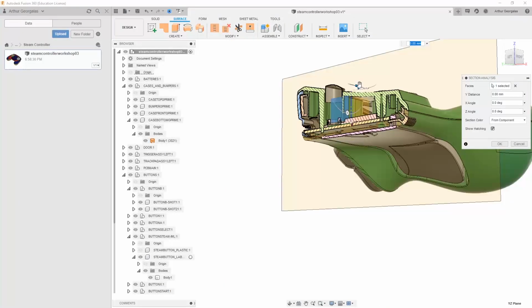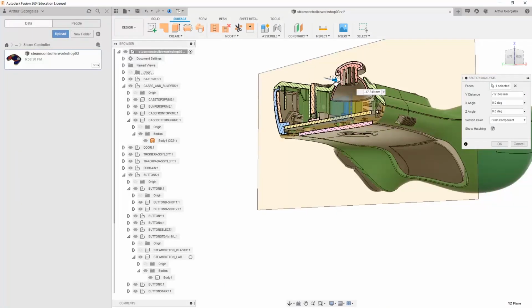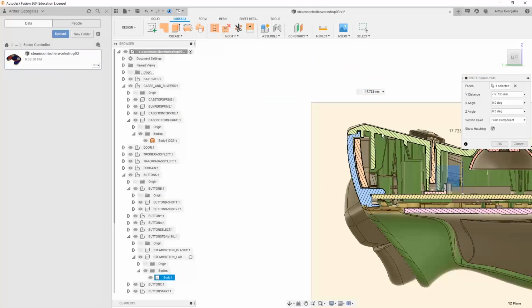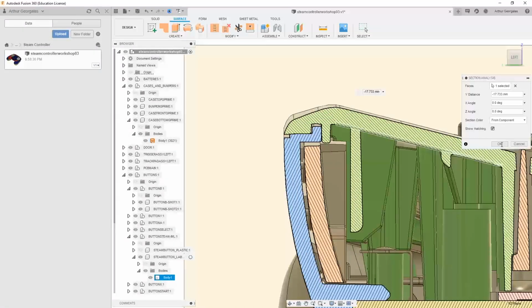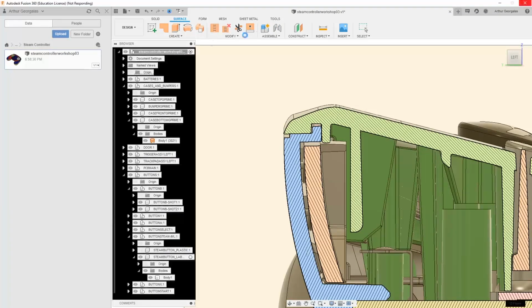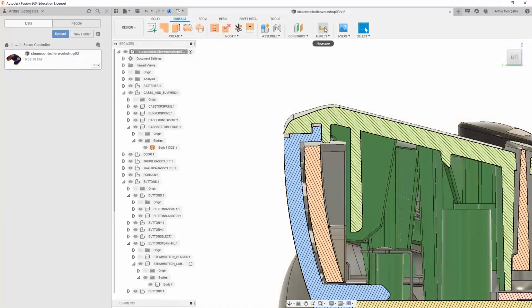What we're actually looking for right here, in terms of what's relevant to us for designing a controller, is the wall thickness. So this one's actually quite thick in its main section compared to some of the other controllers I've seen. Maybe that's why they didn't do so well. The cost was too high or something like that. But generally you'll find controllers aren't more than 1.5, 2 mil thick.